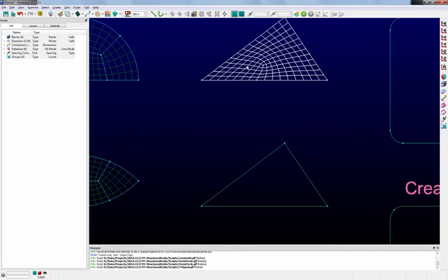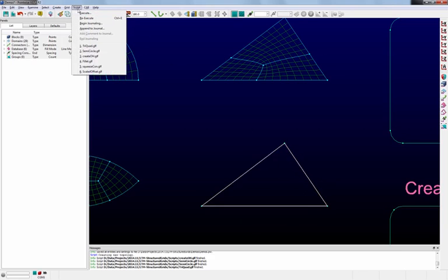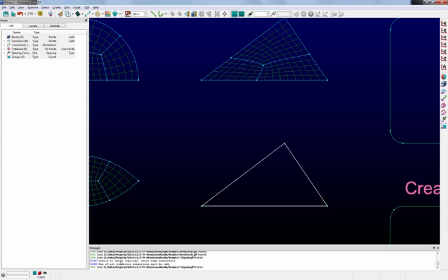Now, as I mentioned before, this is very sensitive to the dimension. If you look down here, whenever I hover my mouse over this connector, it now has a dimension of 14. So it's not dimensionally consistent with that criteria I put forward earlier. If you try to run that same script on this set of connectors, you'll see down here in the message window that the sum of all connector dimensions must be odd. So it's not going to be able to generate that topology for you.